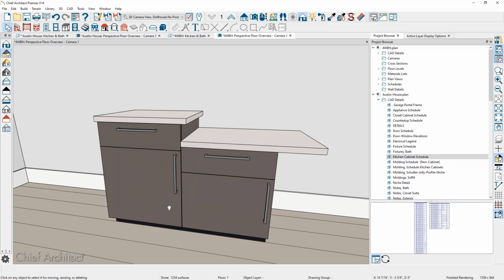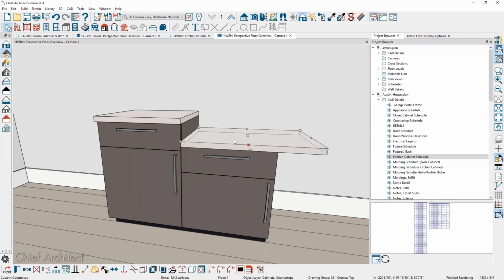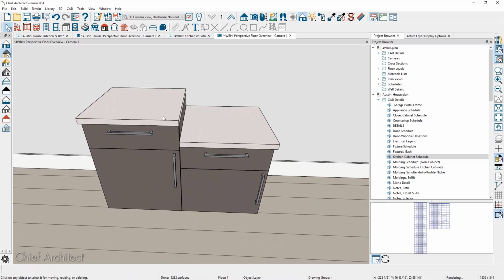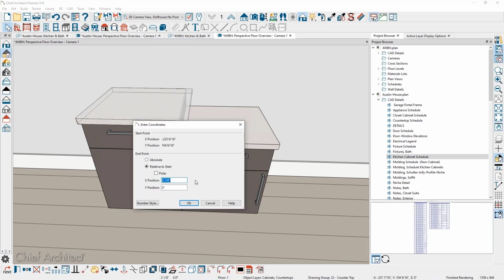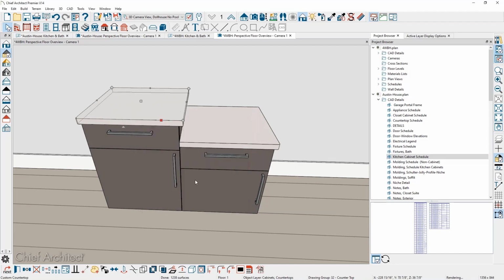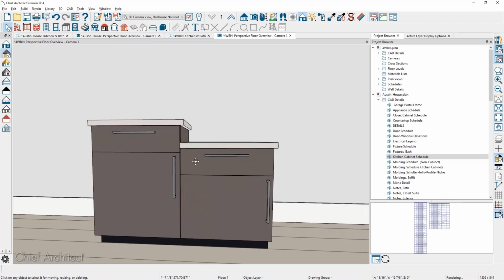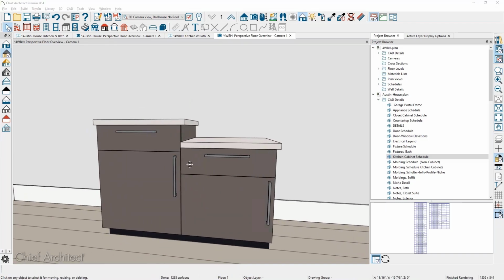I think so. I missed the sleight of hand on that, when you separated the countertop out from that taller cabinet. How did you do that? Click on the cabinet. There's a tool at the bottom that says Generate Custom Countertop. How about that? Separate it. And you can pull it. I use the tab key, and then you can type in a dimension. Well, how about that? Okay. Yeah, that answers my question. Okay, great. Indeed it does.